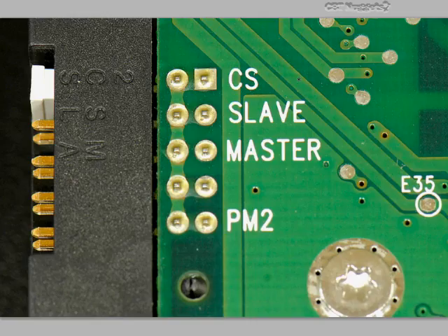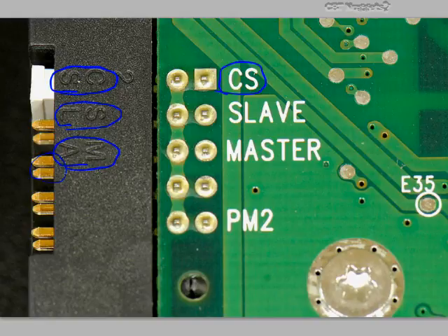And then having tipped the drive up, looking at a different perspective of it, we're looking at the printed circuit board side of this, and there's a couple of different places where it will identify whether or not you want to use cable select, master, or slave. Right now, the jumper appears across these first 2 pins, so it's set at cable select, which you can see there, as well as here on the printed circuit board. If I were to move it over one, it would be in the slave position, and if I were to move it over one more, which would be right here, then that would be the master position. Okay, so that would be at the end of the cable, and of course the slave would be if it were the middle connector on the drive cable.